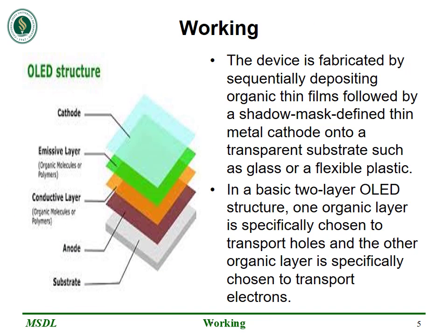So here's the figure which I told you earlier. I kept it here because I wanted to show you guys its structure while I explain how it works. I guess it's easy that way. So an OLED panel is typically composed of four primary layers, which you can see: the substrate, which acts as a structural framework, the anode, which draws electrons, the cathode, which provides electrons, and the organic layer between. This layer is further divided into a conducting layer and an emissive layer.